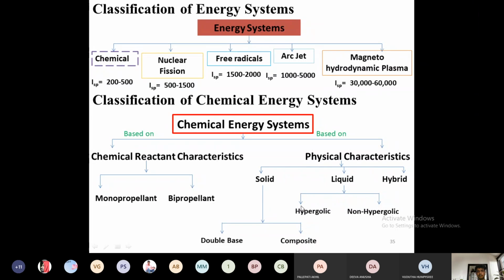When preparing the propellant system, we will use an oxidizer in order to aid the combustion process, and at the same time a fuel as a reducer to be consumed in the reaction. The hypergolic mixture is nothing but a particular mixture which can be spontaneously ignited. Naturally, by its own means, it will ignite.